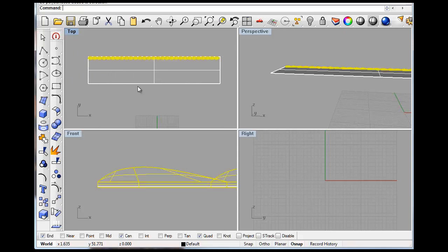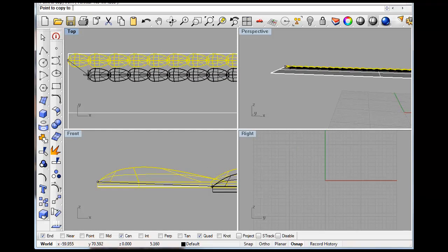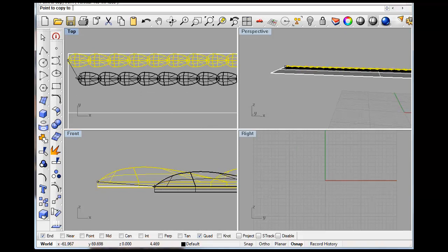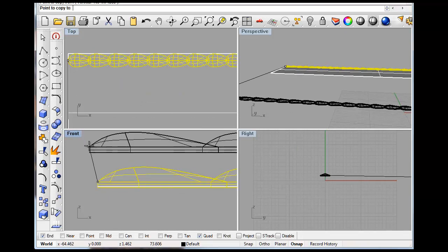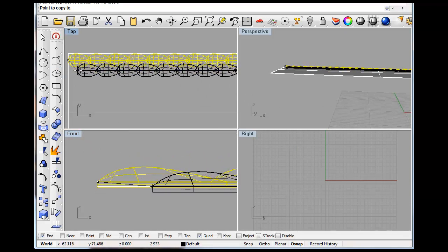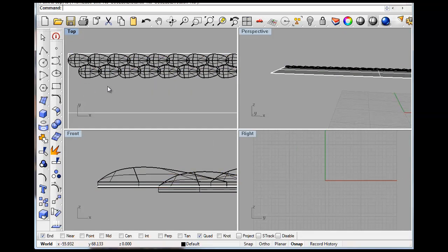We'll copy them. So we'll go from there. Turn that centre off, that's a dead strong snap. Go something like. In fact, if you press Alt, it gets rid of snaps totally while you're just working. So something like that.